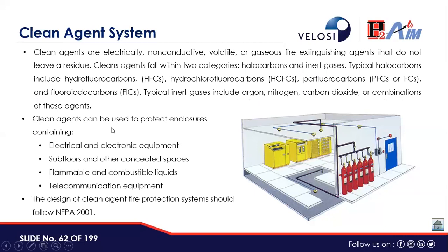Clean agents can be used to protect enclosures containing electrical and electronic equipment, subfloors and other concealed spaces, flammable and combustible liquids, and telecommunication equipment. The design of clean agent fire protection systems normally follows NFPA 2001 requirements.